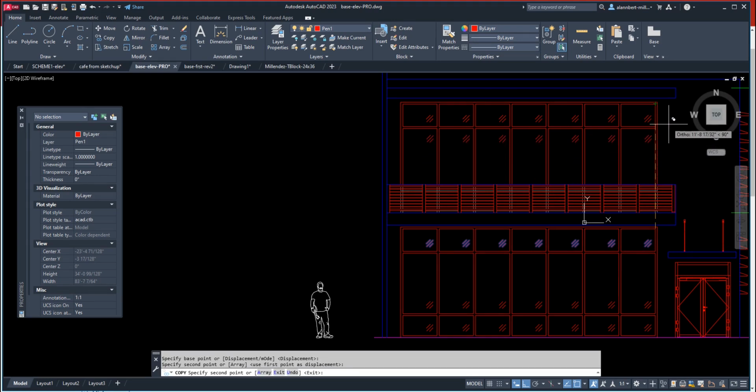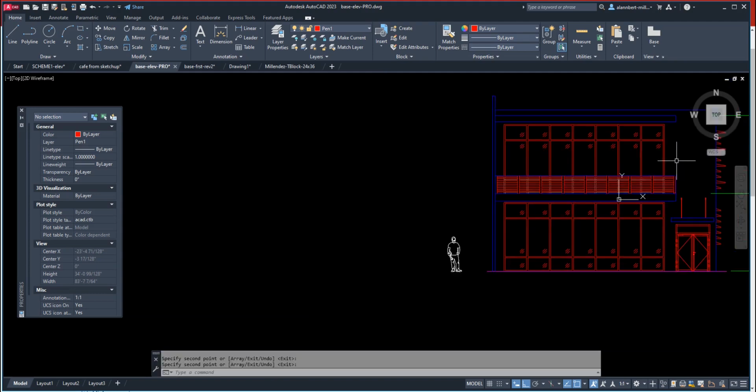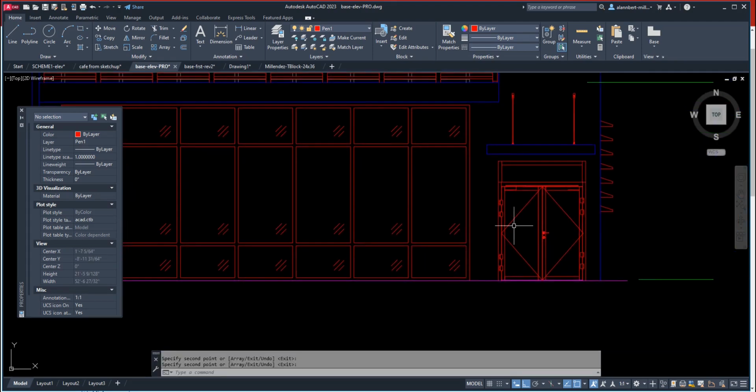We can always put that on top here also. Maybe I like that. Okay. And then this is also glass, so we're going to copy this from here, and now let's put that at the center. There you go. And then simply copy that. Now sometimes you're going to lose your line type, and you can just type in region, press enter, and then it'll bring it back. This one's also glass, and put it there and put it in the center.